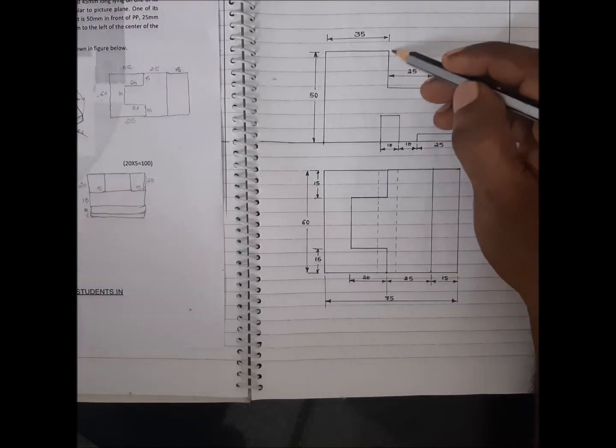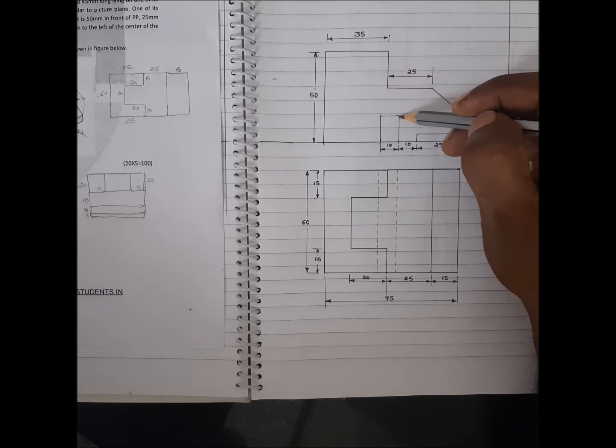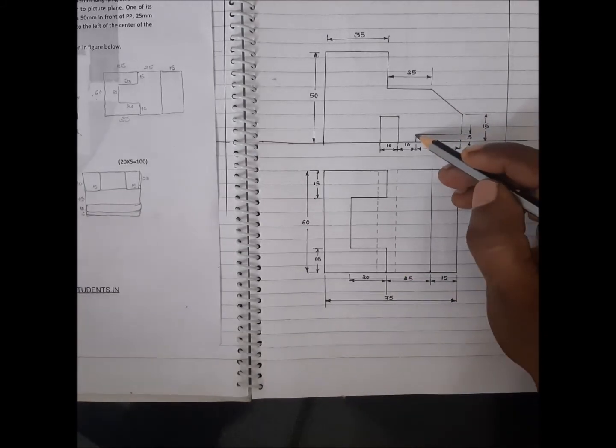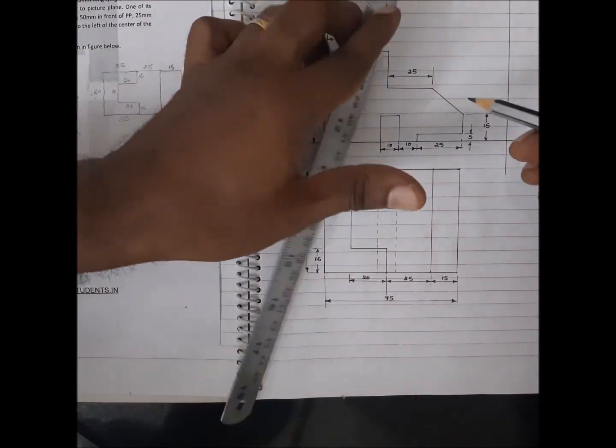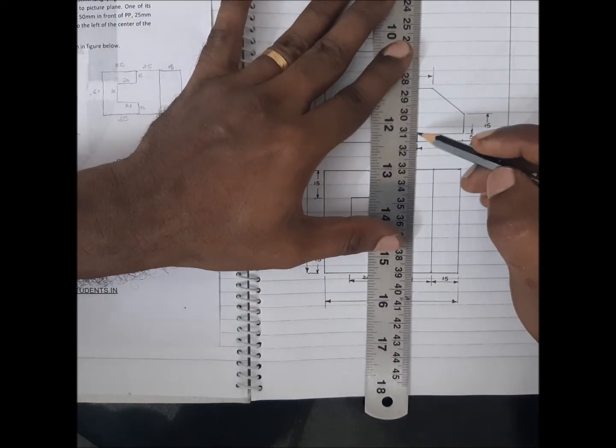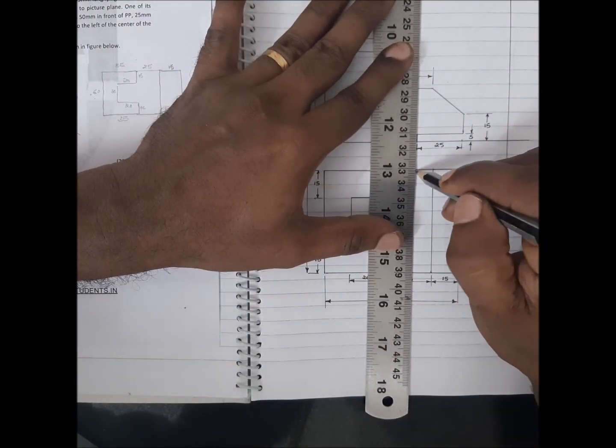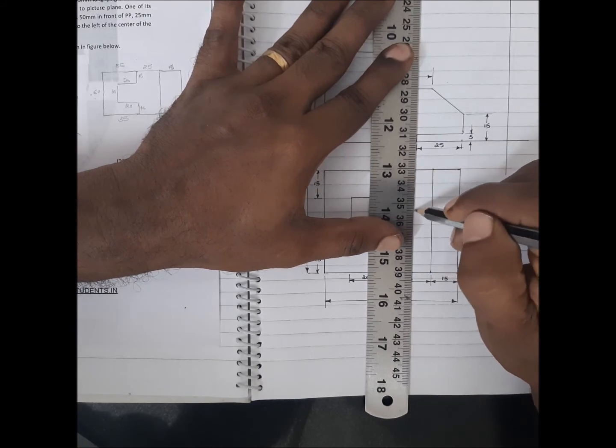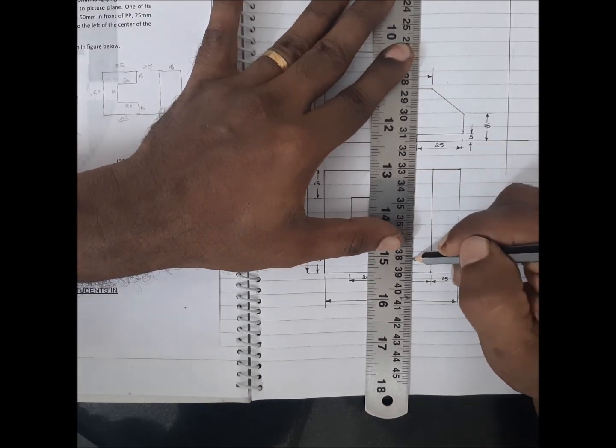What I'm saying is, when you look from here, you can see this edge, you mark this edge, right? Similarly, because of this surface, you can't see this edge, which means that is a hidden edge. A hidden edge should be marked in this fashion. And you can see a hidden edge here also, and that goes all the way through. So all these hidden edges should be shown as a dashed line.